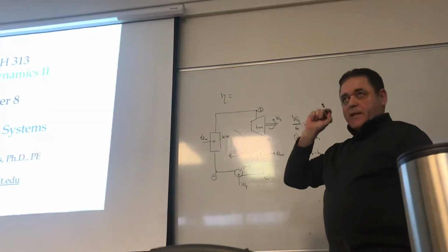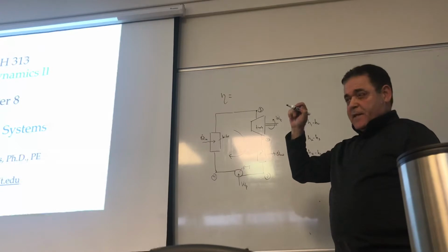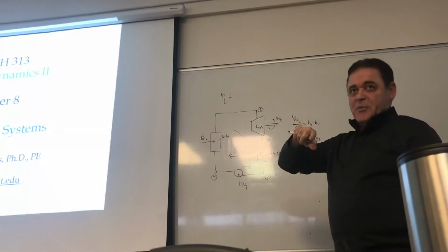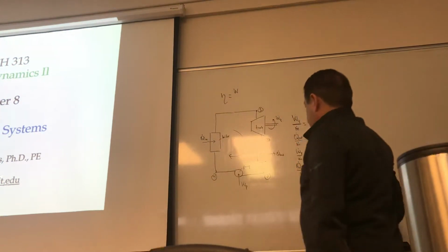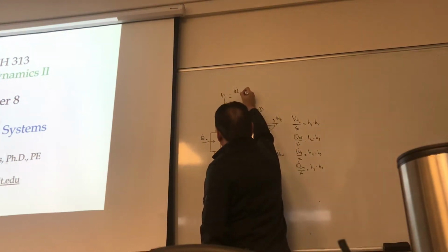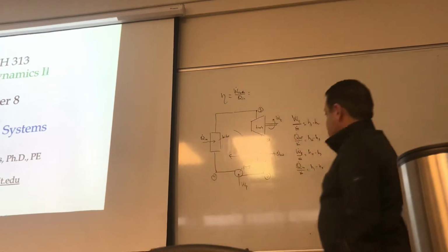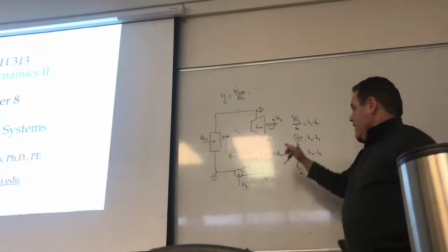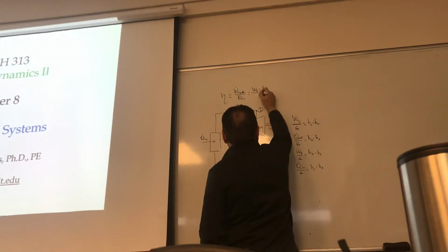If you were to just say, without again looking at the book, I'm just going to find an expression for the efficiency, okay? It's output divided by input, right? So it's W, but what kind of W? I have 2 W's in here. Well, it's W cycle, you're right, divided by Q in, right? But W cycle is equal to what? W T minus W P. So the net work that you're getting is really WT minus WP. See, this one I'm paying, I'm not getting, right?